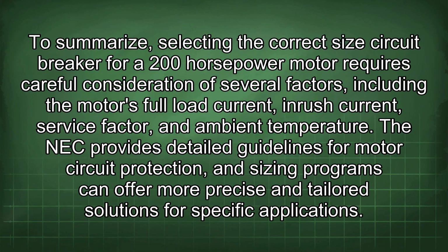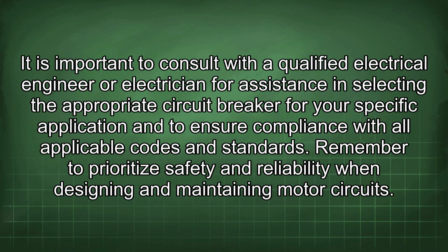To summarize, selecting the correct size circuit breaker for a 200 horsepower motor requires careful consideration of several factors, including the motor's full load current, inrush current, service factor, and ambient temperature. The NEC provides detailed guidelines for motor circuit protection, and sizing programs can offer more precise and tailored solutions for specific applications. It is important to consult with a qualified electrical engineer or electrician for assistance in selecting the appropriate circuit breaker for your specific application and to ensure compliance with all applicable codes and standards. Remember to prioritize safety and reliability when designing and maintaining motor circuits.